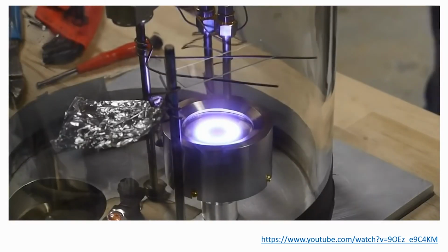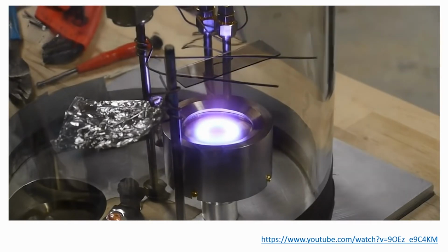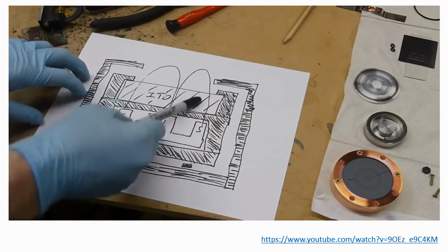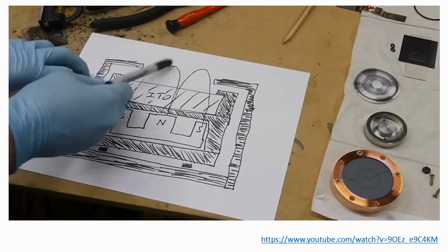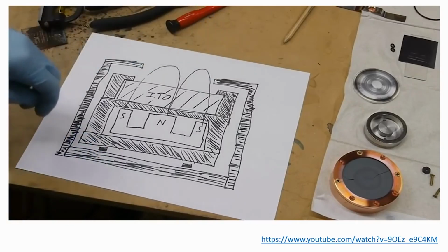So when we pump down the chamber to a very low pressure and put our 1,000 volt potential difference on here, the remaining gas molecules in the chamber will ionize, basically just like they do in a neon sign. The trick with the magnet is that it concentrates all of the electrons in this area. It does this because the electrons are relatively lightweight and they have charge, so the moving electrons are affected by these magnetic field lines. In fact, they actually spiral around the magnetic field lines. So we've concentrated all the electrons in this area.